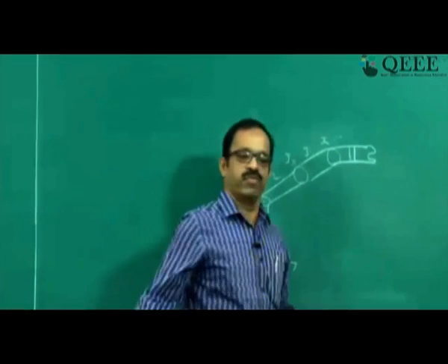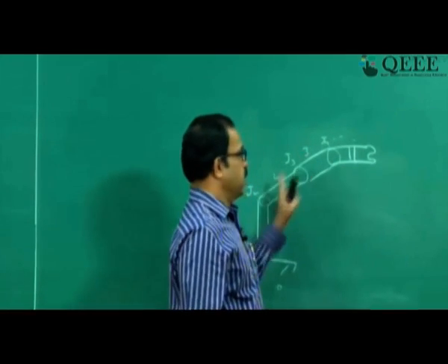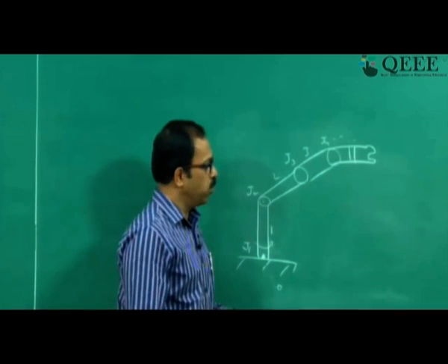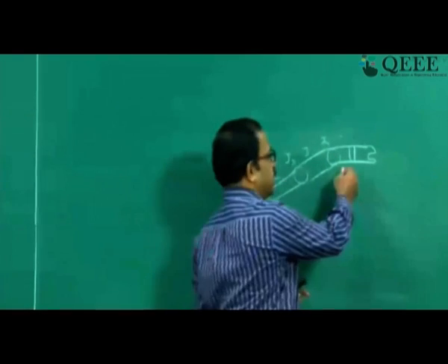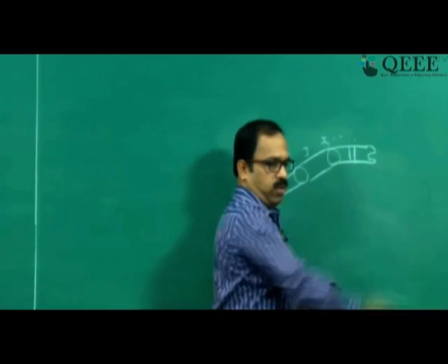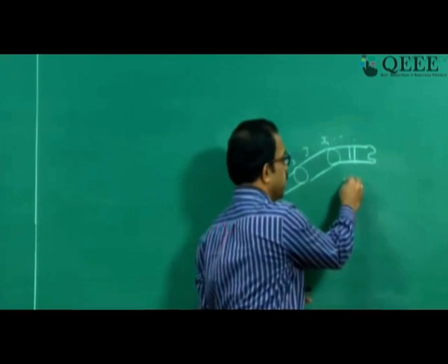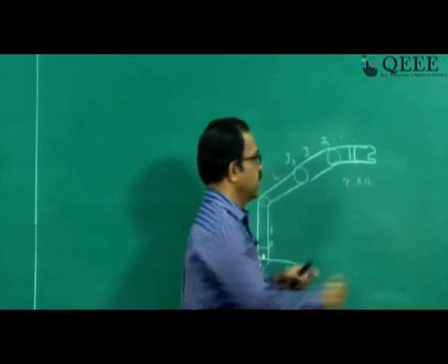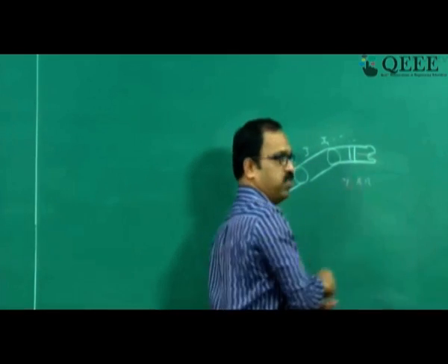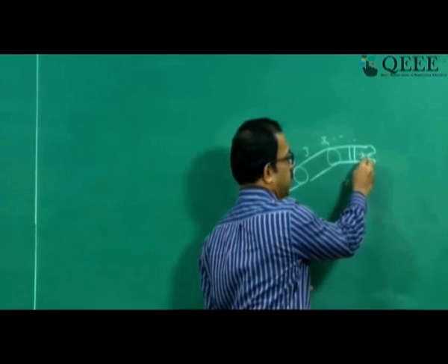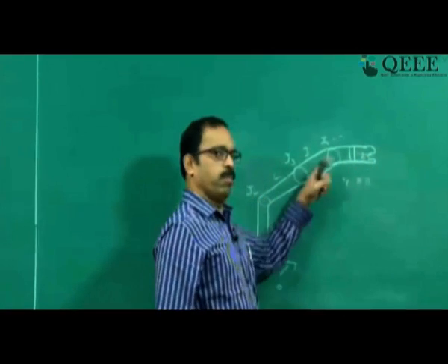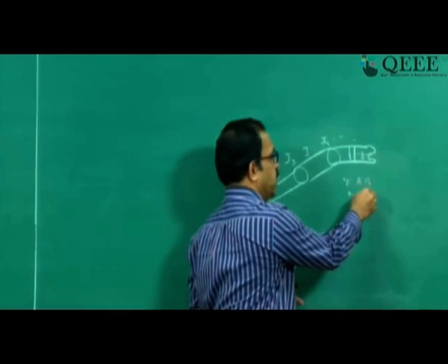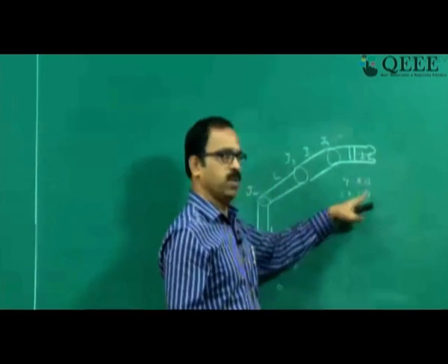Normally in a 6 degrees of freedom manipulator, you will have the first 3 joints for positioning and the last 3 for orientation. That is like yaw, pitch, and roll, in that order. The roll axis, which is the rotation with respect to this axis, will be the last one. So basically, with respect to X, Y and Z, the rotations we normally call yaw, pitch, roll.